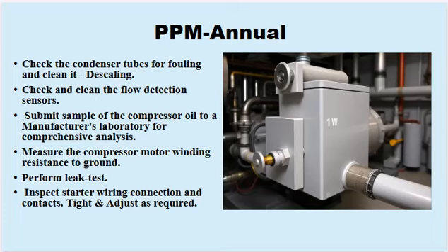The flow detection sensors must be checked and cleaned to ensure accurate flow monitoring. A sample of the compressor oil should be submitted to the manufacturer's laboratory for comprehensive analysis to determine its condition and suitability for continued use. The compressor motor winding resistance to ground must be measured to ensure electrical integrity. A complete leak test of the system should be performed to identify and address any refrigerant leaks. The starter wiring connections and contacts require inspection, tightening, and adjustment as needed to maintain proper electrical connections and prevent